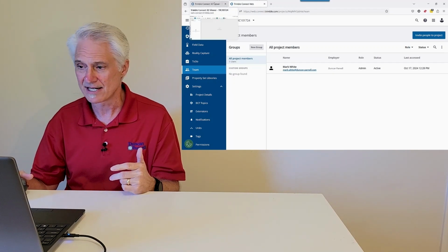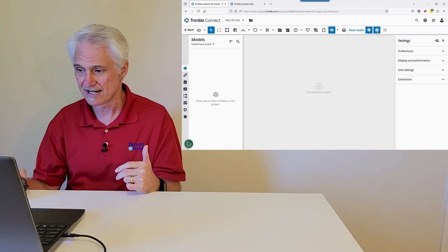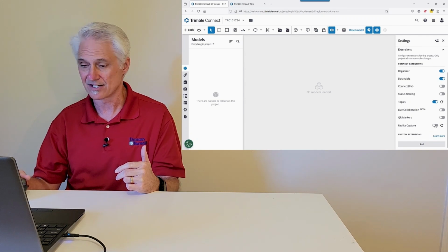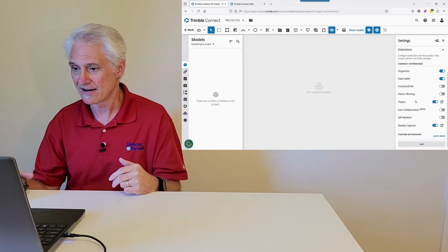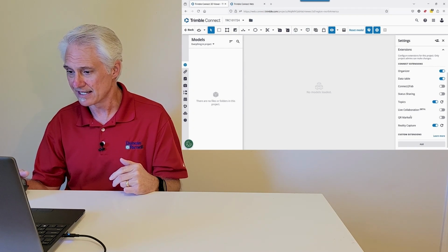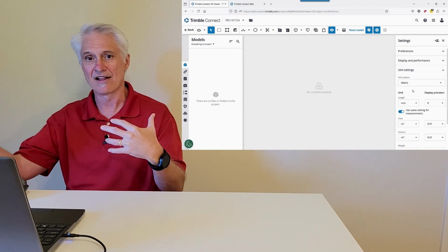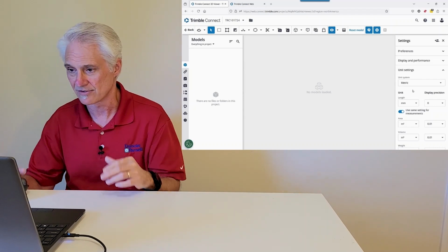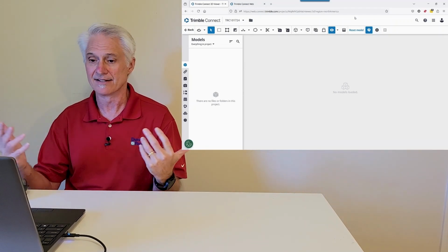And then in the 3D view, I'll come over to the settings over here and again, turn on that reality capture extension if you want to view it in 3D, okay? So we'll look at it there. And then also, again, you can do your units as well. If I go up here, there's my unit settings. I want them to match. Whatever I've got in the file system or file space, I want it to match in model space, okay? So make sure those match up. But then once you get those set, you're all ready. You're ready to put data in there, okay?